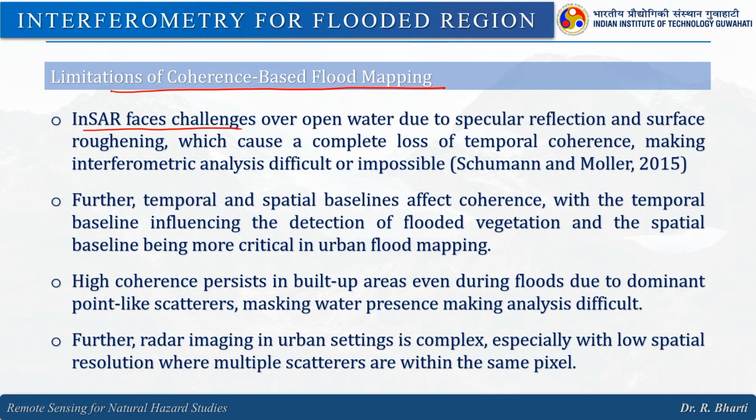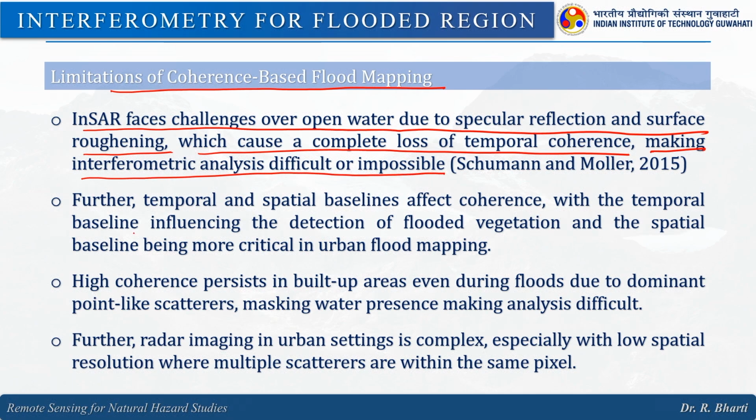Limitations of coherence based flood mapping. InSAR faces challenges over open water due to specular reflection and surface roughening, which cause a complete loss of temporal coherence, making interferometric analysis difficult or impossible.